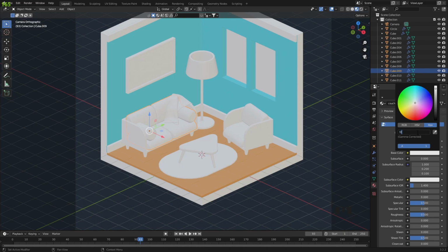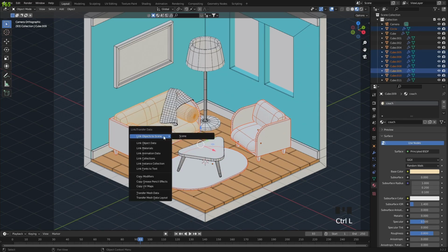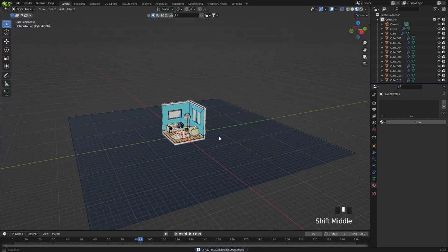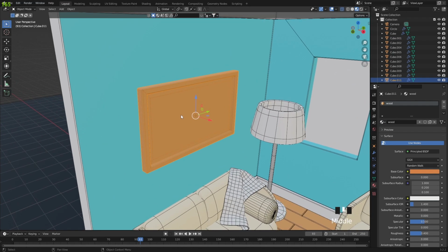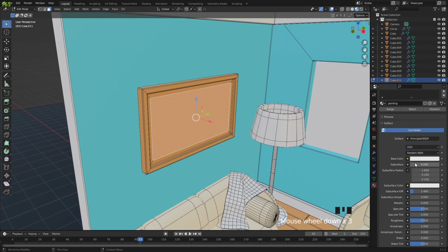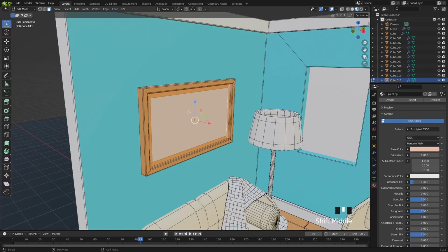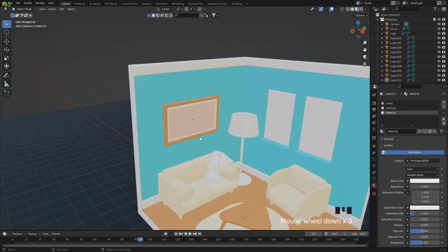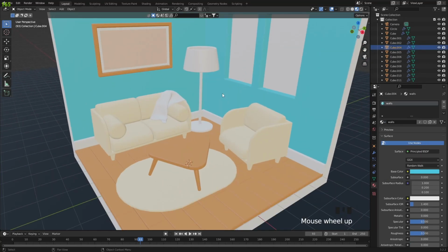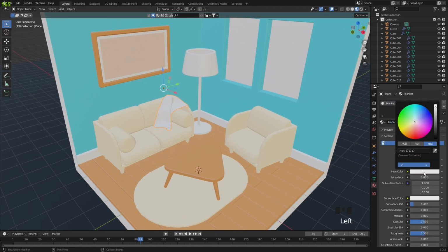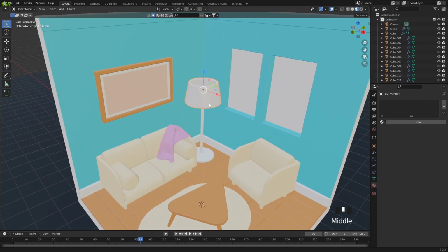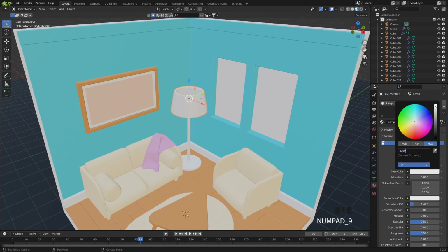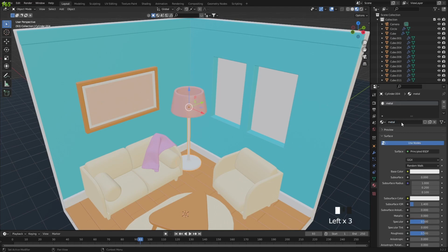For easier material distribution, select all the objects you want to color the same, then select lastly the object which you want to copy the materials from, then press Ctrl L and select Copy Materials. I hope that you could manage to add the materials to everything.